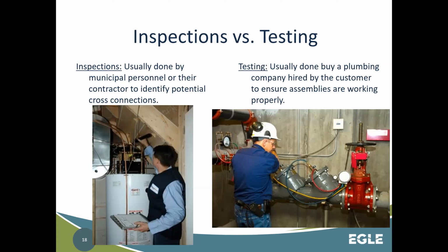Now, Michigan does not recognize, in industrial and commercial settings, a backflow assembly being repaired by anyone but a licensed plumber. We do not recognize the ASSE repair certification. Okay, just so we're aware on that. But testing has to be done by an ASSE 5110 certified tester. Sometimes those people are not licensed plumbers and they don't have to be.